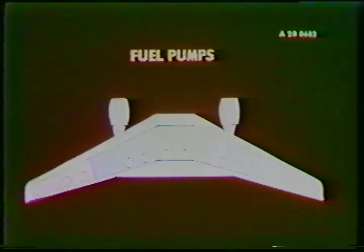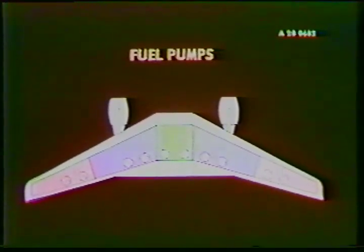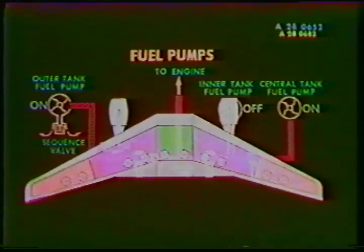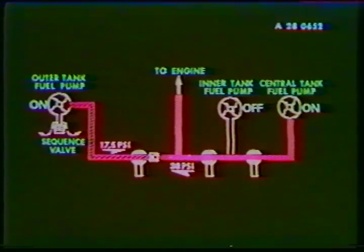2 submerged fuel pumps are located in each tank, and for structural reasons, the center tank is to be used first, and then the inner tanks must be emptied before using the outer tanks. This fuel management is automatically accomplished by an electronic system between the center tank and the inner tanks, and by sequence valves between the inner tanks and the outer tanks. The sequence valves are fitted to the outer tank fuel pumps.